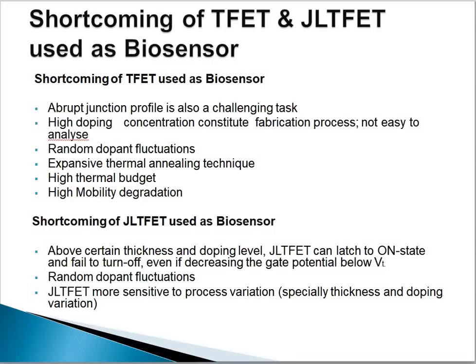In this slide, we are discussing the shortcomings of the TFET and junctionless TFET based biosensor. Shortcomings of the doped TFET biosensor. First one, the abrupt junction profile is a very challenging task. Second, high doping concentration makes the fabrication process not easy to analyze. Third one, random dopant fluctuation.